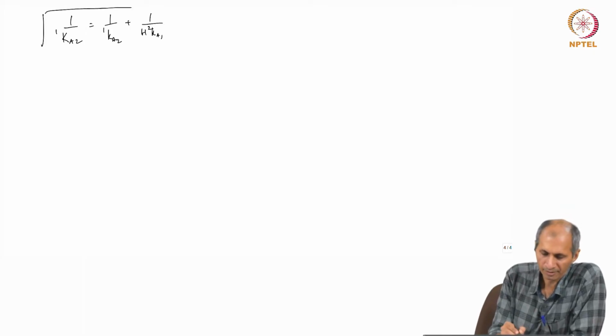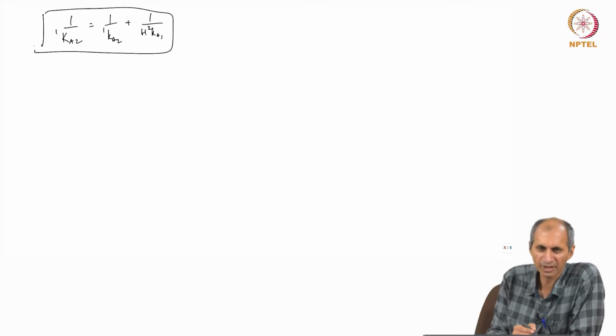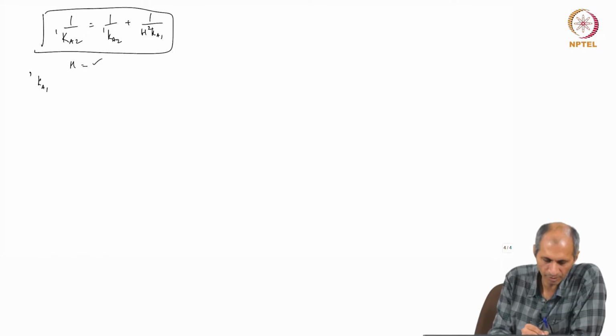So, now this is the next step. We have the driving force in place, and this is the next step. So, this you have to calculate. Henry's constant is already known, should be known for the chemical you are looking at. The mass transfer coefficients Ka12 and Ka21 are to be obtained from correlation.